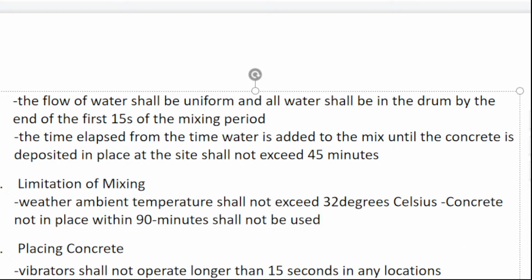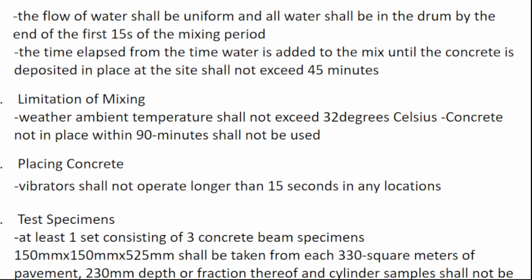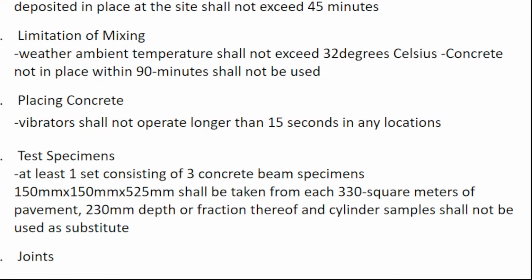Okay. So, number 5, placing of concrete. Vibrator shall not operate longer than 15 seconds in any location. So, per location, 15 seconds, 15 seconds, and so on. Any location, point to point. Point to point. 15 seconds and 15 seconds.